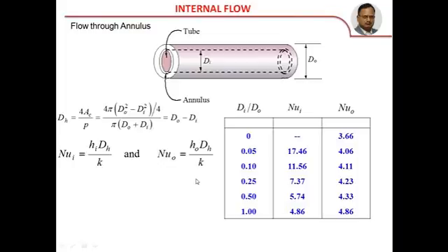In case of rough pipes, instead of going for a calculation, you can also use the chart developed by Moody. It is a simple thing. So with the help of that F, you can determine the friction, and then due to that friction coefficient, the head loss due to friction and the power loss for pumping the fluid, you can determine. This is more or less related to a fluid mechanics problem in flow through pipes.